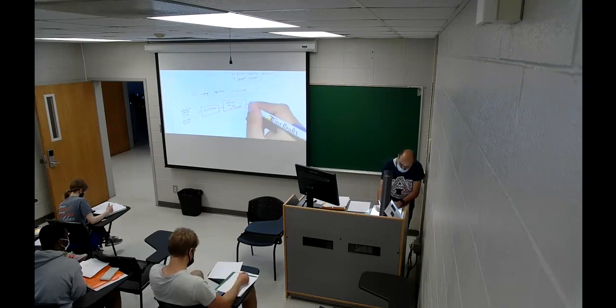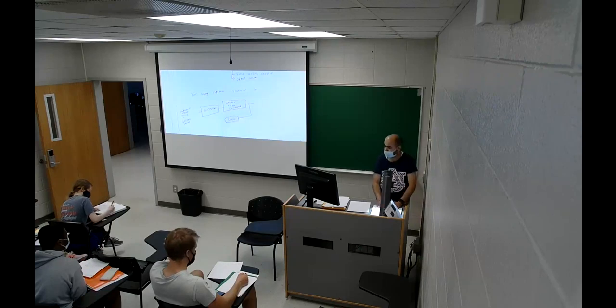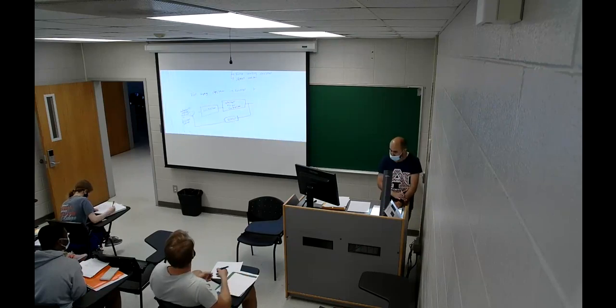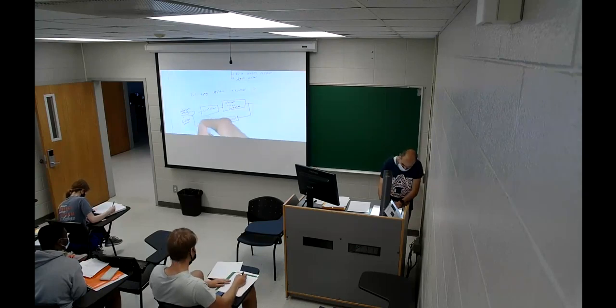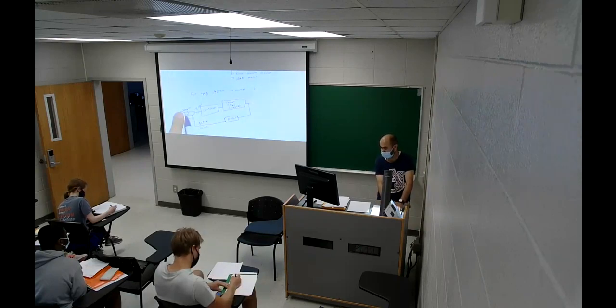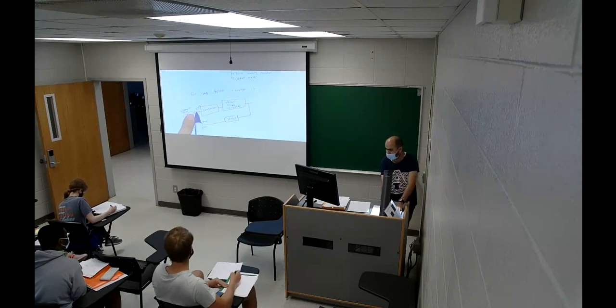So we call it feedback. So, sensor. After that, I compare my desired value with the actual value. So find the actual speed. Then the error will go to the control signal. For example, the actual speed is 0 and the desired speed is 70 miles per hour. Then what's the error? It's 70. So I'm pressing high on the accelerator.